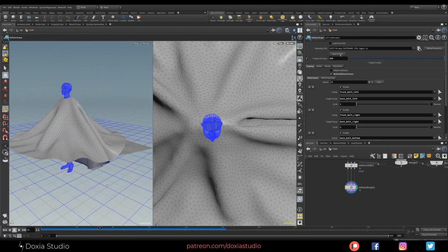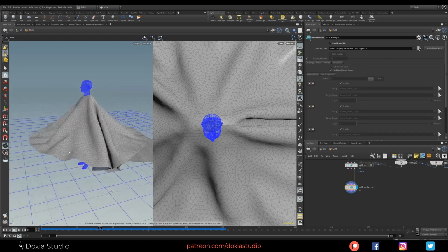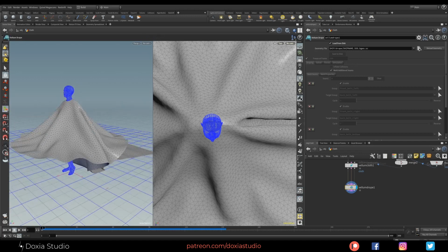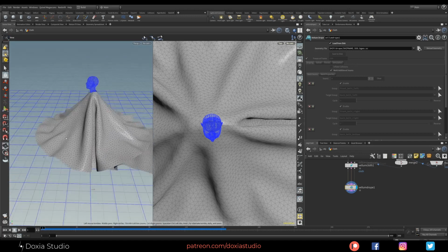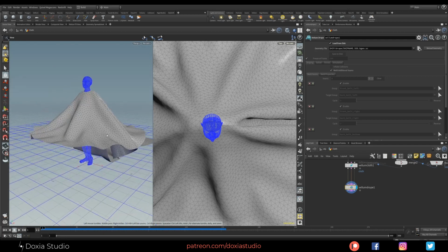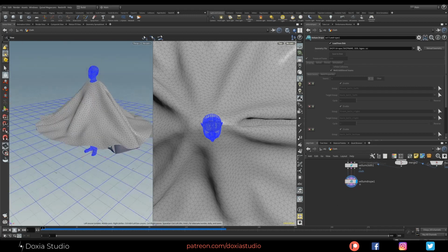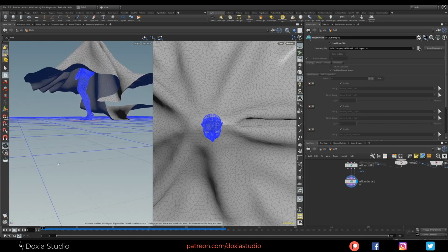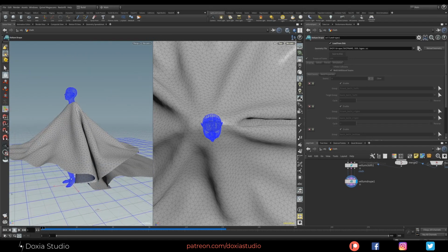Okay. One thing I like to do is save to disk and load from disk, just in case we don't change anything and it's loading from the disk and it is faster. Okay, right now we won't lose anything. Okay, so we have our cloth. We need to do a few things first before our simulation, just in case, to prevent these from exploding.